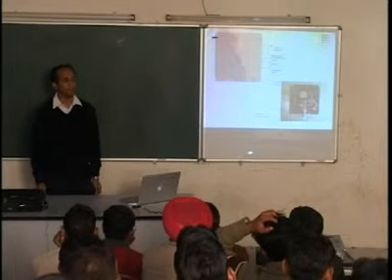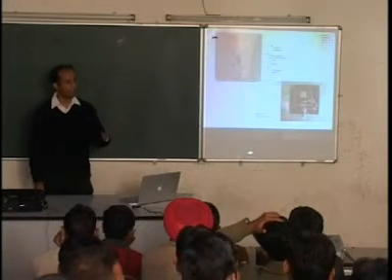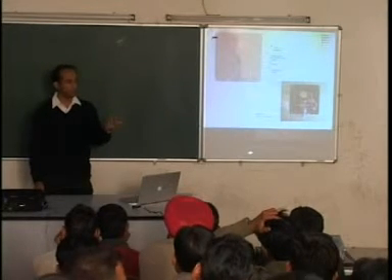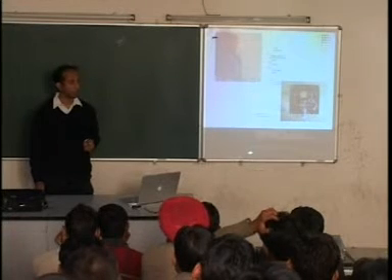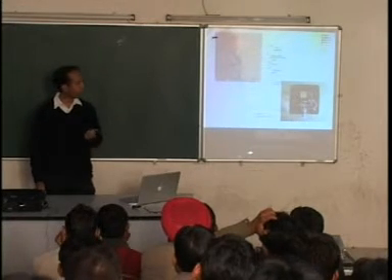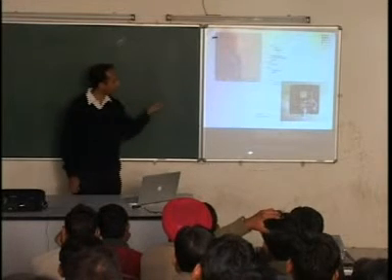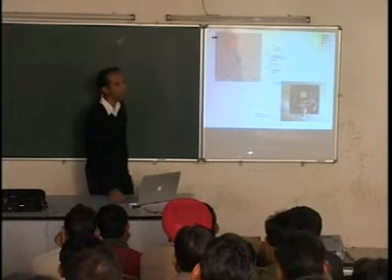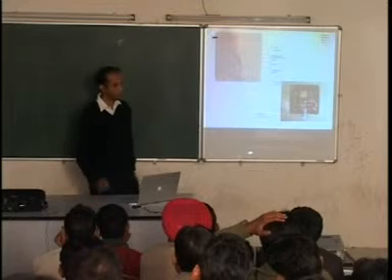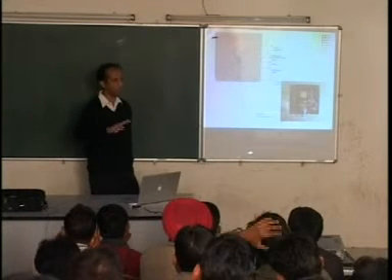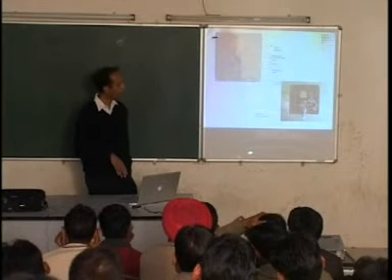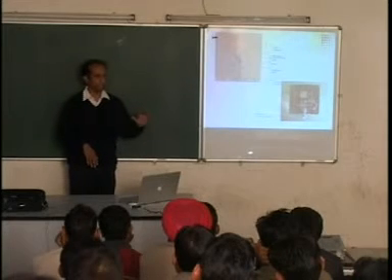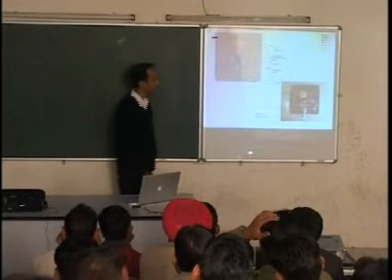What is the effect of that? Effect is that below that patch, effectively the dielectric constant now becomes almost 1. There is hardly anything there, just 10 micron is a very small number. Okay? Just that much of silicon. Just barely enough to support that patch. And actually it is too little, it's not practical. Okay? If you leave that thing due to temperature changes, it will buckle and eventually break. Okay? So it is just for demonstration. Okay? If you actually want to make it, there are other techniques. You don't use it, there are advanced techniques to do this, but it does work.